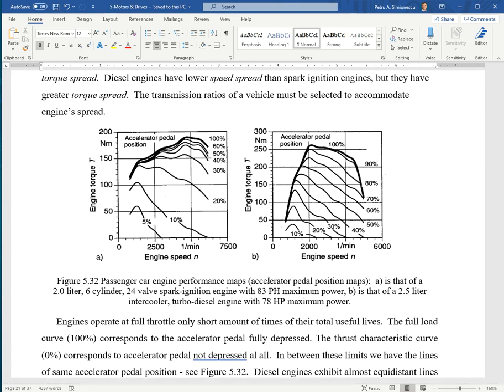Maybe an aircraft engine, small aircraft engine, you force it full throttle for a few tenths of a second when you take off, and then when cruising, you reduce it to 60-65%, and it's also for fuel efficiency reasons, as well as extending the life of the engine, not overheating, not overloading the bearings and parts.